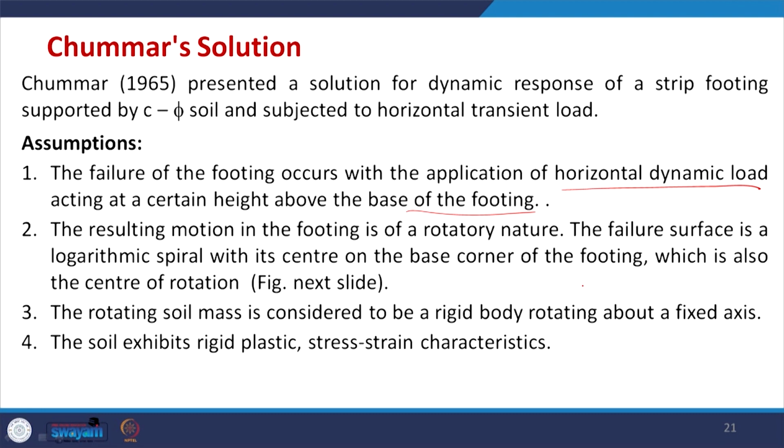So, fixed axis, which we have already discussed, means that the center of rotation is already fixed, and this will be treated as rigid body motion. The soil exhibits rigid plastic stress strain characteristics, which is the case for all the 3 theories. So, all the 3 theories which we have discussed so far assume that the stress-strain characteristic is perfectly plastic. Under these assumptions we go for the Terzaghi solution.